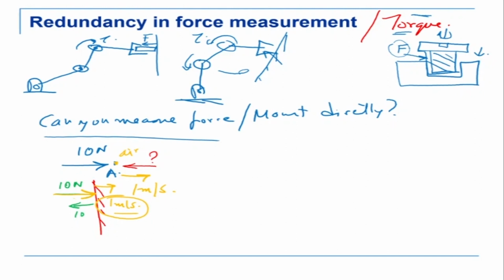This is very important and interesting to understand: when can you apply a force and when can you apply a velocity? Can you do both of them in the same direction? No, you cannot. Force and velocity cannot be controlled in the same direction. That means on a wall, for example, if I press, I can apply a force, but I cannot control a velocity in that same direction.